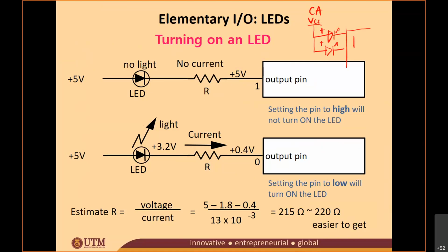So this is your port. You connect your port to your microprocessor. In order to turn this LED on, you need to give your port output 0. Why? Because VCC is logic high, and the current only flows if there is a difference from high to low, from 1 to 0. When the current flows from 1 to 0, your LED will turn on.